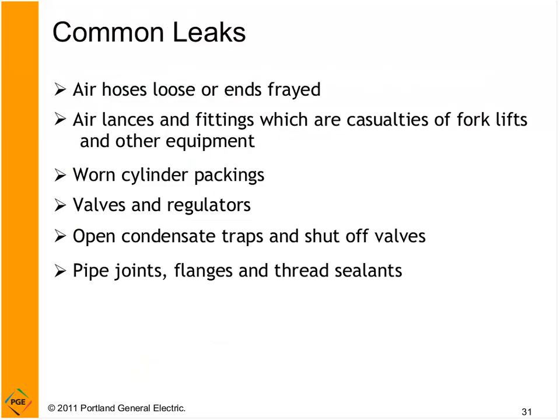Sources of leaks. Okay, we have Mr. Forklift driving over hoses, worn cylinder packings. Okay, even gaskets between joints. Sawmills are banging around and eventually gaskets leak. Open condensate traps. That's a big one. Let's just walk over and crack open the bottom of that drain or the bottom of that filter so that it drains all the time, blowing valuable compressed air.